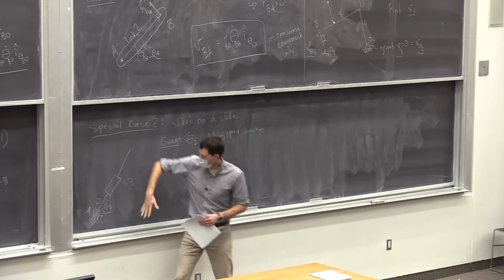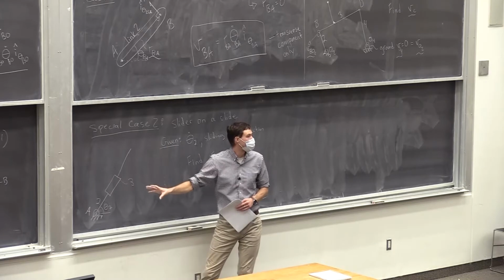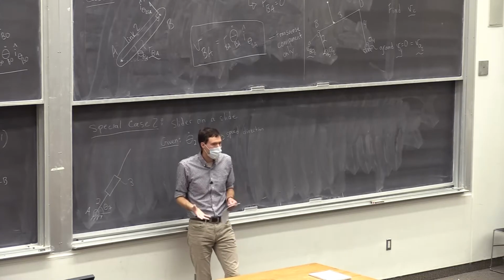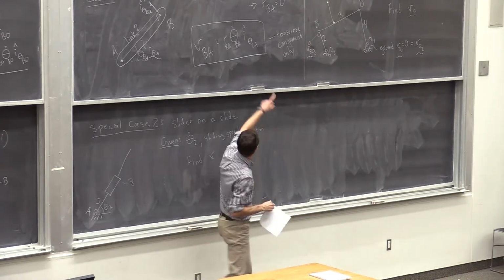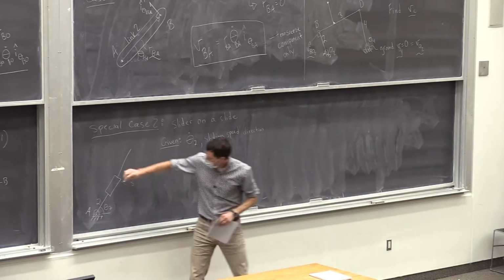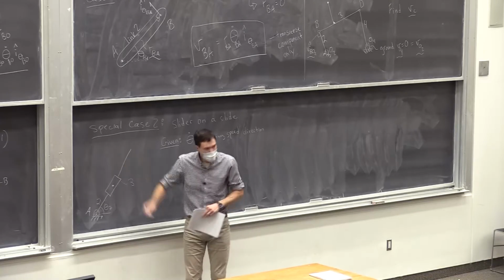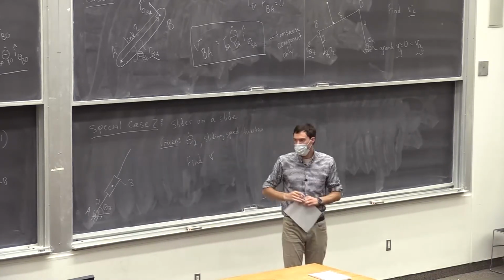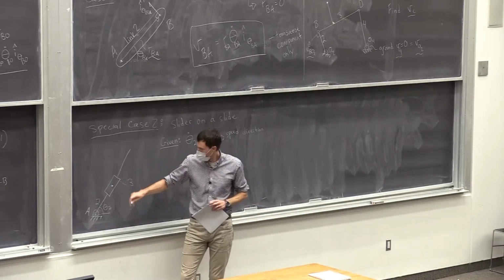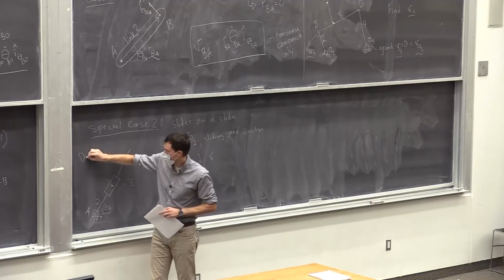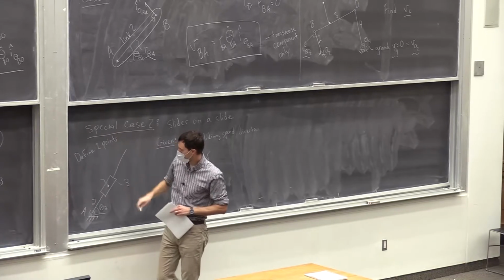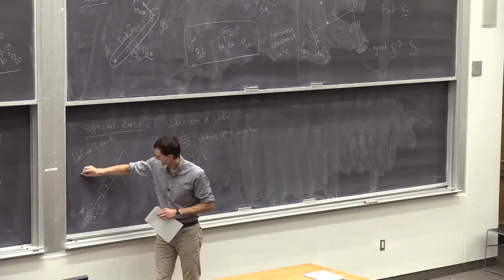So link 3 is sort of rotating and translating at the same time. This is a difficult combo, right? Rotation plus translation, there's a lot going on there. So just like we did with our case 1, we're going to break up the solution into 2 steps. And our trick that we're going to pull, and this is what I suggest you do for every slider case, is let's define a special pair of points right here. We're going to define a pair of points, 2 points, right at that location. We're going to call them points B.